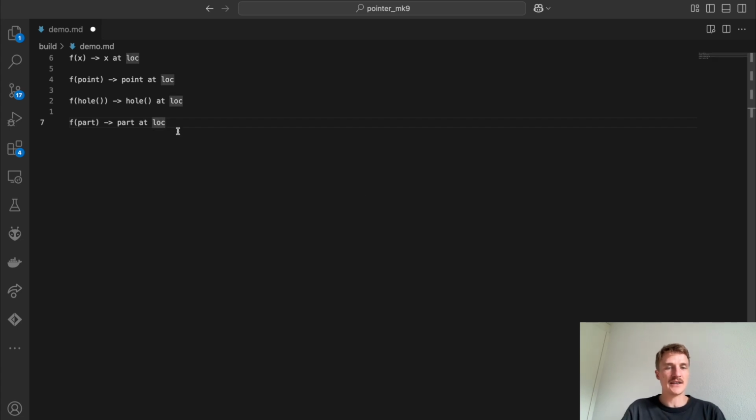And so hopefully you can see here that this doesn't require any dependency on the previous step, because if you want to define a sketch, it only depends on the function f. And if you want to define a geometry, you can also just call a given function. And if you want to define an assembly, same thing, you can just call this function. And so now if we want to change your sketches, your geometry, and your assembly, you can just modify the function f, and it's going to impact all of those without having dependencies between them.